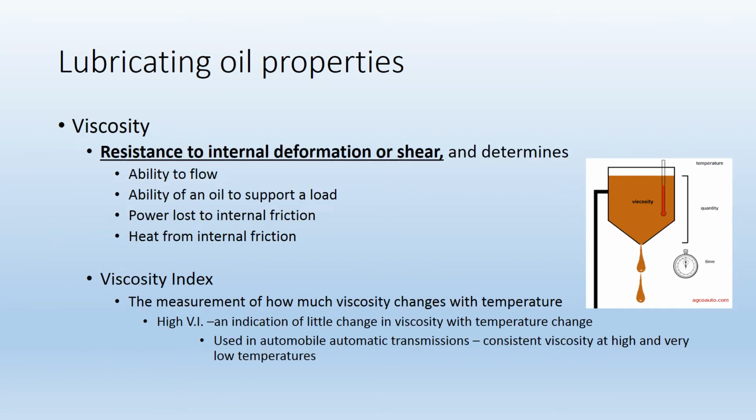Viscosity is the resistance to internal deformation or shear, and this viscosity will determine the ability of a fluid to flow, also the ability of the fluid to support a load, the power loss due to internal friction, and the heat generated from that internal friction. Just remember that definition for viscosity for your government examination. Viscosity is the resistance to internal deformation or shear.